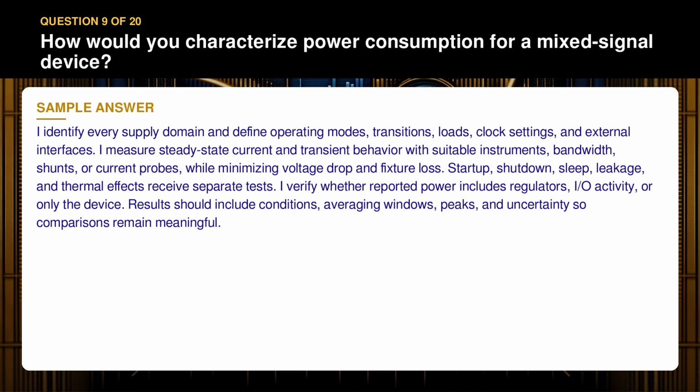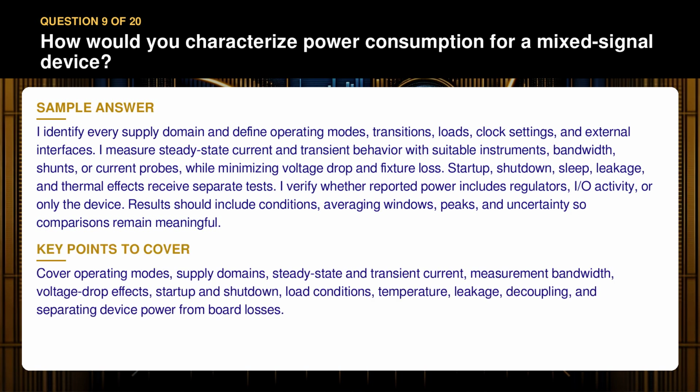I verify whether reported power includes regulators, I/O activity, or only the device. Results should include conditions, averaging windows, peaks, and uncertainty so comparisons remain meaningful. Cover operating modes, supply domains, steady-state and transient current, measurement bandwidth, voltage drop effects, startup and shutdown, load conditions, temperature, leakage, decoupling, and separating device power from board losses.